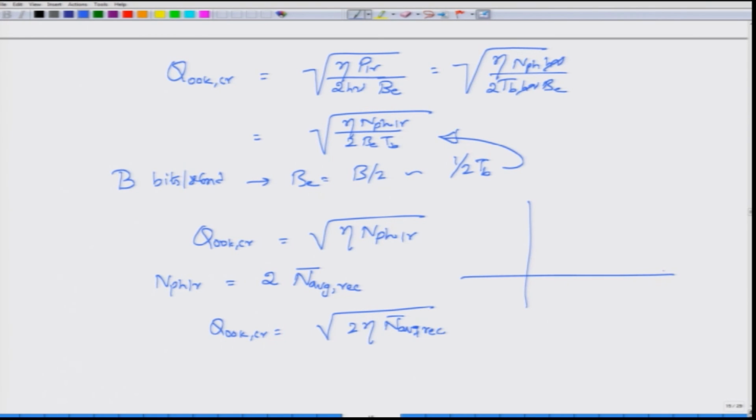If you quickly evaluate this, you will see that the BER of course increases, but there is a 3 dB improvement between the direct detection receiver and the coherent receiver, which is operating under the shot noise limit, as the fiber length increases. You will also see that approximately the length with the coherent receiver will be twice the length with the direct detection receiver, and all this is happening because you are using this extra degree of freedom because of the coherent receiver. Okay, we will stop at this point and consider the limitations due to dispersion in the next module. Thank you very much.